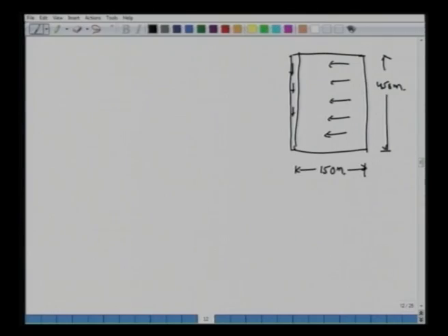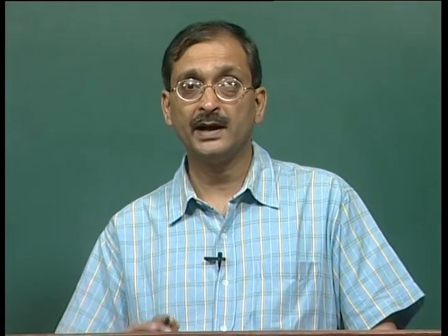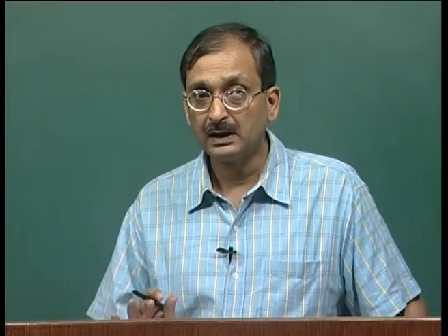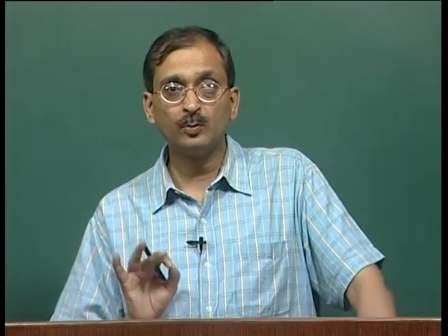What are the isochrones? Isochrones are the lines joining equal times of travel. So, whenever we have to do contouring, what do you do on a map? You put the benchmarks, or you put certain spot elevations. So, in any kind of problem similar to this, at some points on this graph, you put the travel times which are available to you.